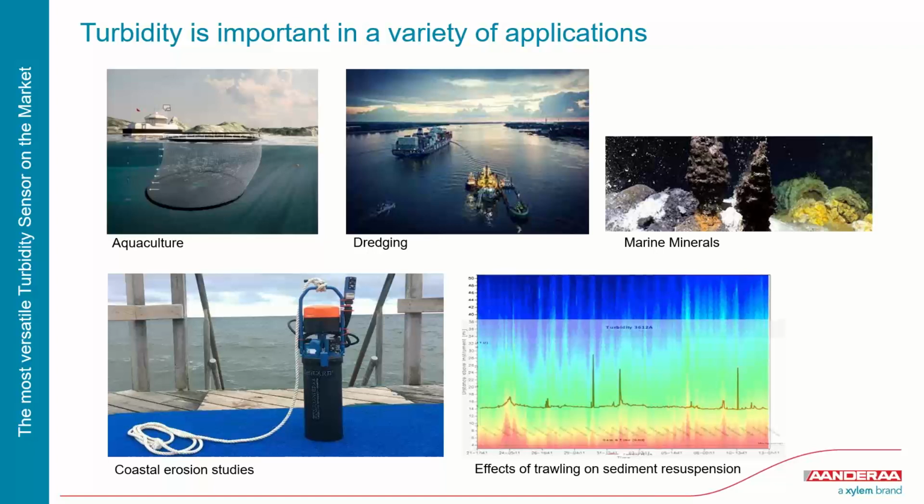Then where turbidity is really important is in dredging, isn't that so, Inger? Yes, and we worked over the years with dredgers with many different parameters. In dredging, obviously, monitoring the suspension of the sediments while you're doing the dredging activity, making sure it doesn't become too high and cause life-threatening situations for the ecosystems surrounding the site, is of vital importance. They use these sensors to give very rapid updates on the status around the site. And in the up-and-coming marine minerals industry, it's a similar problem, right, Anders?